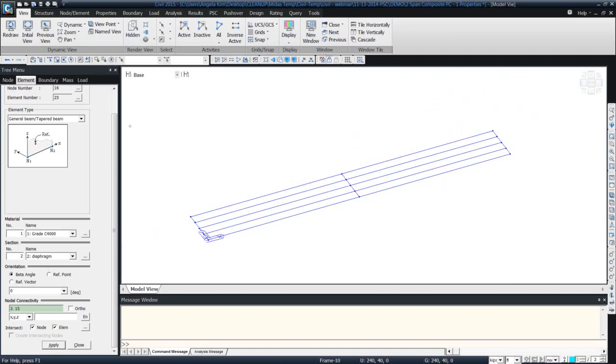And now our girder is total 320 feet long, but right now I only have 2 elements for each span. That is not really the optimum condition for the finite element analysis, since the program calculates the value at the end of each element at each node. So if I only have 1 element per a longer length, it means that the accuracy goes down.